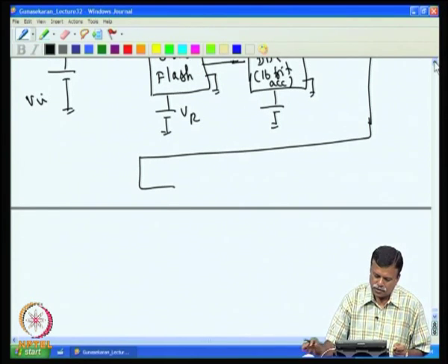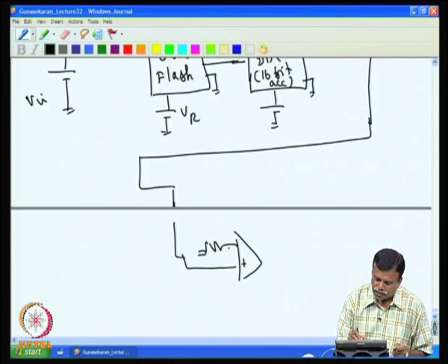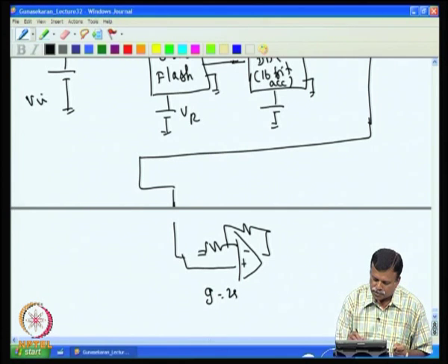So, we can get into the next page. We will have the amplified voltage coming here. Here we amplify this, say for example, for another 8 bit converter I need to amplify by 256 times, gain equal to 256.